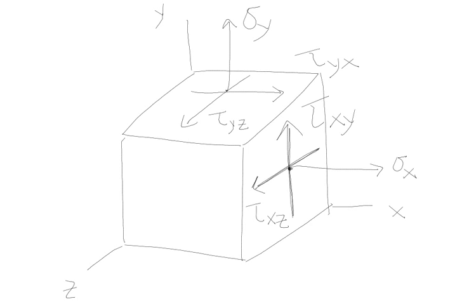Then I'm going to go to this front face. I have my sigma z. Notice I'm drawing all my sigmas as being tensile. It doesn't matter, they could be compressive as well. This is tau z face y direction. This is tau z face x direction. And then I left out the other 3 faces, but you could imagine the same things going on in those 3 faces.